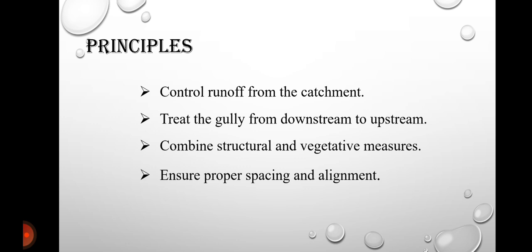It may control the erosion. They should prevent further erosion of the gully bed and the side slopes. It may trap the sediment. The structures should allow the soil particles carried by the runoff to settle and to accumulate. Stabilize the gully: the gully bed and the banks should be protected from further damage.